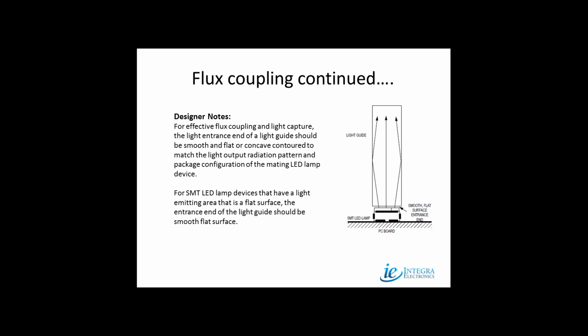And in practice, that's generally not true. The surface mount LEDs in particular are a challenge because typically there's no lens or focusing on the LED itself. And so the light is actually coming out 60, 70, 80 degrees off axis. Some of it, of course, is coming straight up, but a lot of the light is coming in at a wider emission angle. And so the light going through the light pipe is not all just going smoothly straight down the middle. And this becomes important later when you talk about how to channel the light through the light pipe and out to the other end. Thanks, Mark.